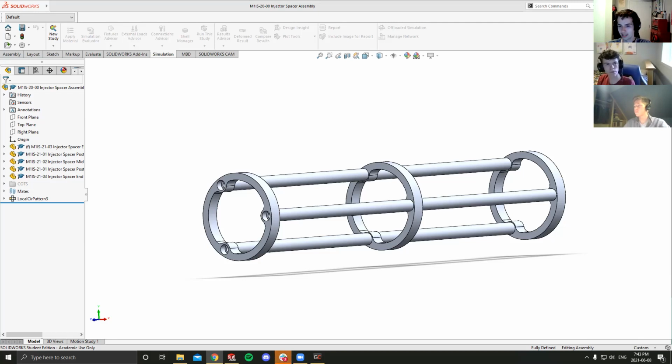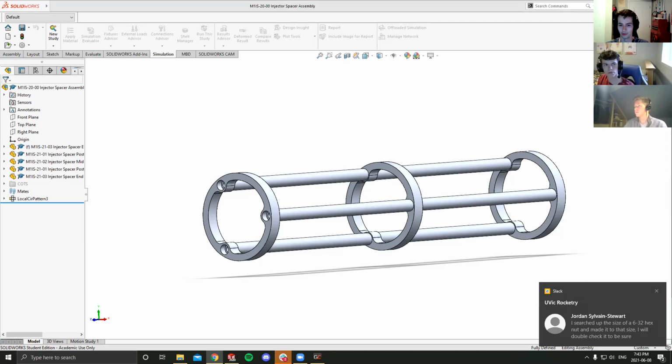You may have some weird geometry that can make stress singularities, I think Claire called them, where you have a zero or very, very minuscule amount of material, and that is a stress concentration that infinitesimally builds as the amount of load that's applied increases. And so that can skew your results. And obviously, again, we don't want to blindly trust our simulations. So those should be verified.